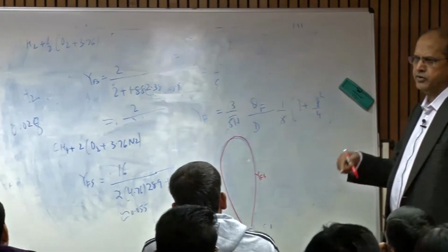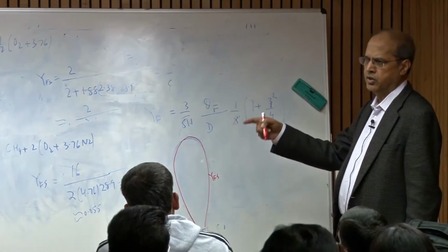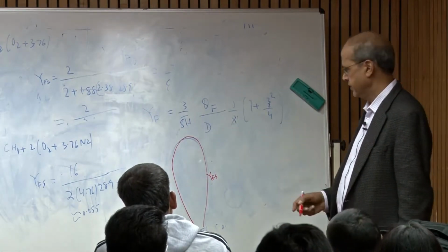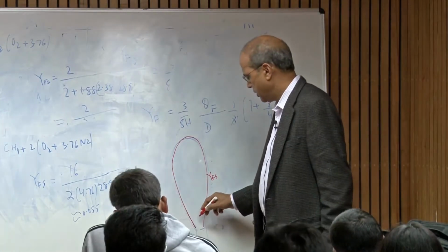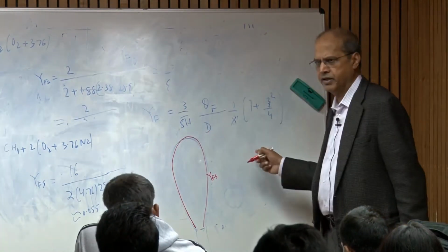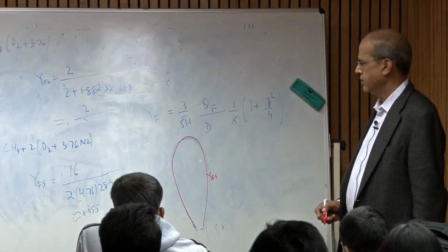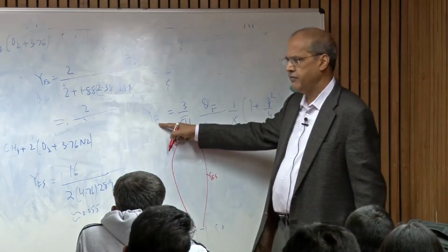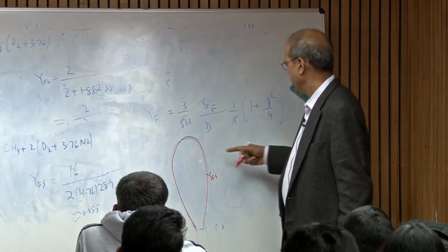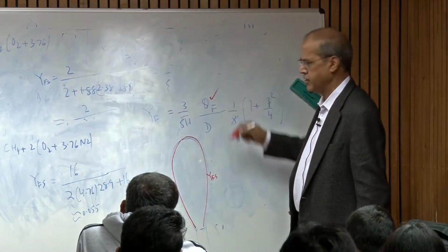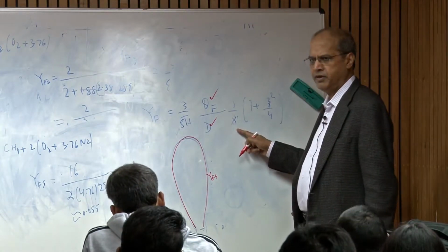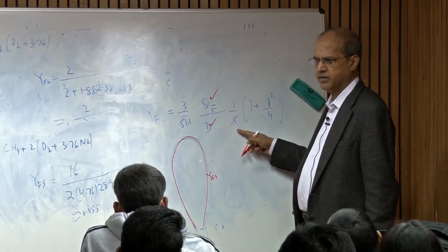The flame surface is located along the loci of YF equal to YFS. If you plot the contours of YF, because this equation gives us the contours of YF, all you do is take any value of YF, let's say 0.9. Then QF and diffusivity are constant, and this gives you an equation between R and X.